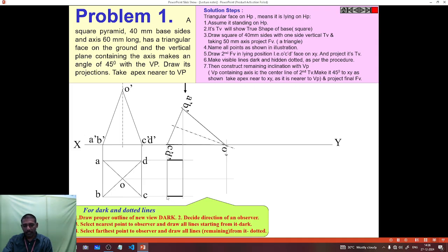We put the C point here. Next, we put the B point here, at the B horizontal line and B vertical extension line. Similarly for A. Next, the A, O horizontal line and vertical extension line, we put the O here. So this is the simple projection of the solid.